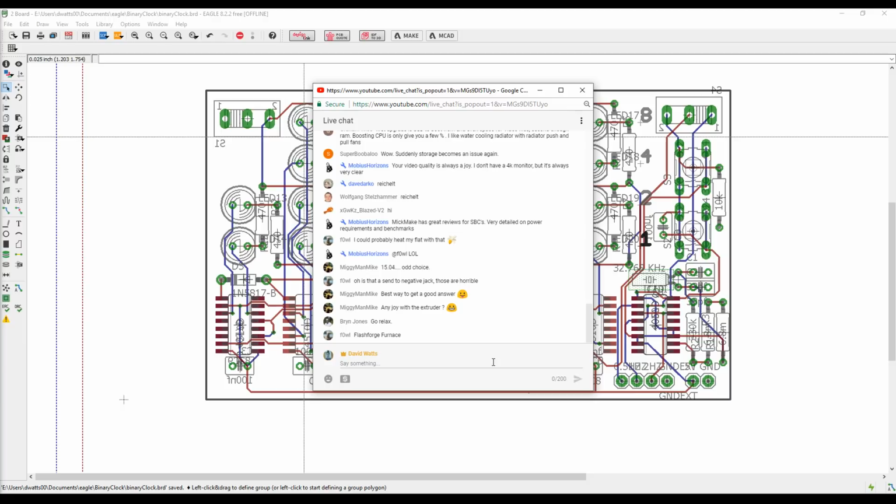I didn't know whether it was not hot enough. I'd already cleaned the extruder cog thing, the little grippy wheel that's on the end of the servo. I cleaned that with a wire brush, and scraped inside with a pair of sharp end tweezers. I'd been through, cleaned the extruder out. I bought some tools, so they've arrived. So I'm going to see if I can clean that extruder a little bit more, the nozzle. But I'd put some glow-in-the-dark filament through as well, which is coarser, so it can help clean out the nozzle. And nothing was working.